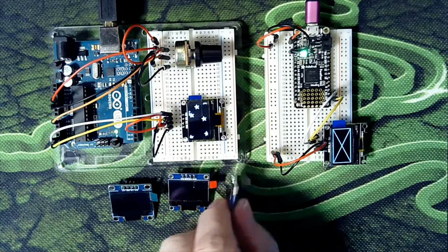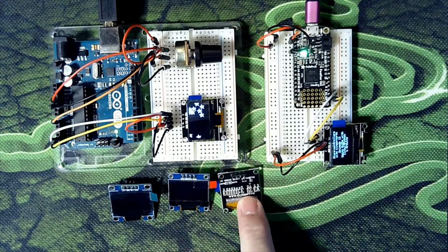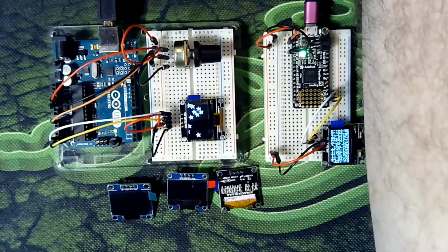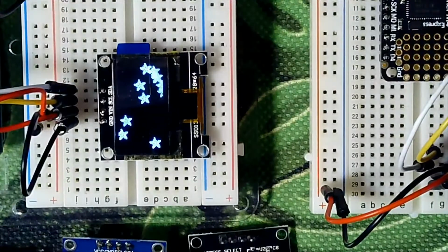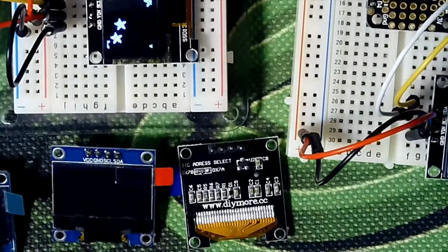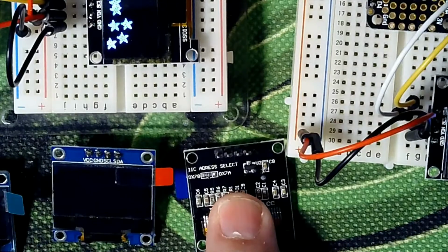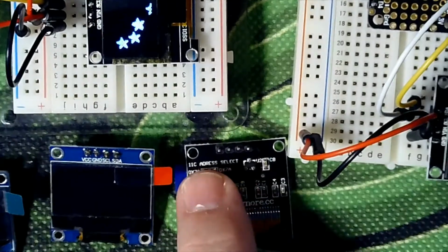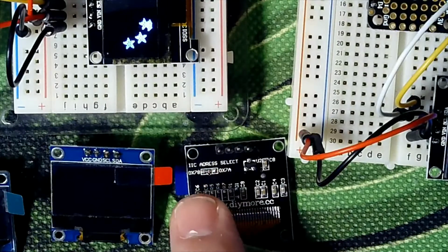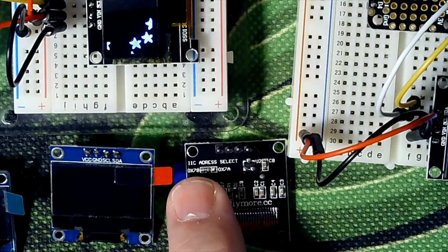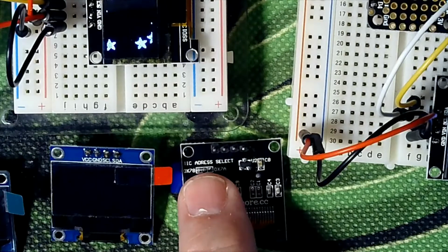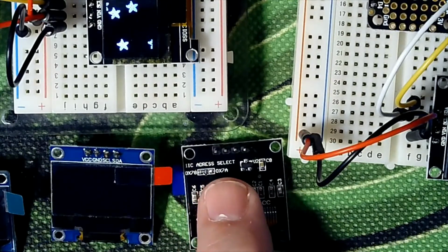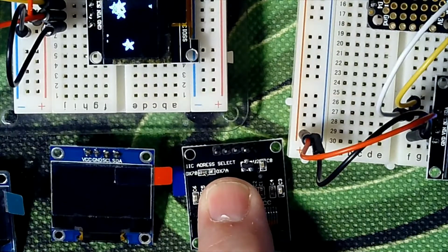Now these, if you flip them over, we can see on the back, and in fact, let me just zoom in a bit here so we can really get a good look at that. And we'll just move them accordingly. We can see that there's addresses on the back. The address is already listed there. It's IIC or I2C, address select. Now it says that it's 0x78, and there's a little resistor that jumps across that gap, or you put it across the other gap, you unsolder it and move it over, and it should be 0x7A.